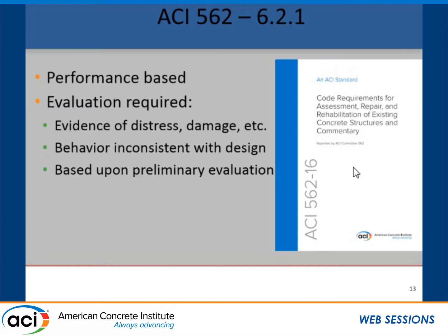I looked at that slab edge, I showed you that picture of that slab edge earlier. It sure as heck wasn't supposed to be a 2.5-inch deflection over 10 feet. That sure wasn't consistent with the design, but there was no distress associated with it. So I knew, through figuring things out and looking, there's no cracking, no distress. I knew that the guy screwed the formwork up. It was pretty obvious, but I needed to make sure of that because the behavior was inconsistent with the design.